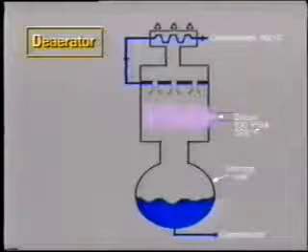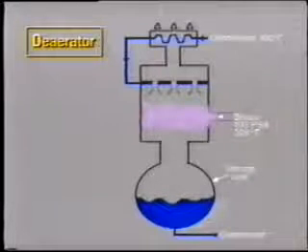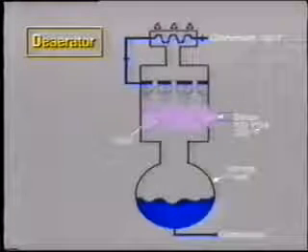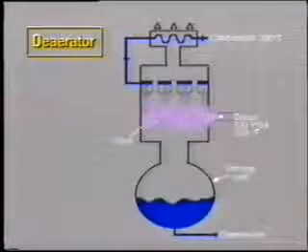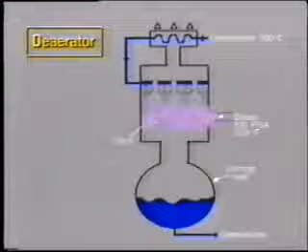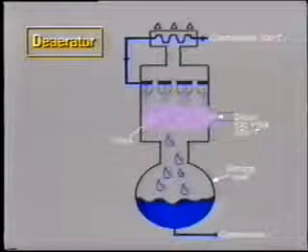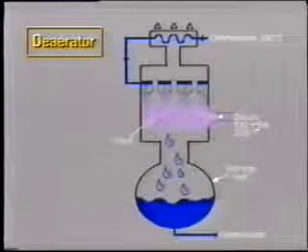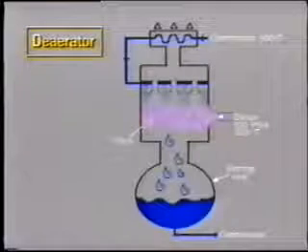As the water enters the de-aerator under pressure, it is sprayed into the tray section. From here, the water droplets pass over trays, all the time mixing with steam, eventually falling into the storage tank. The steam and water become mixed, with the steam condensing and the water temperature increasing close to saturation.